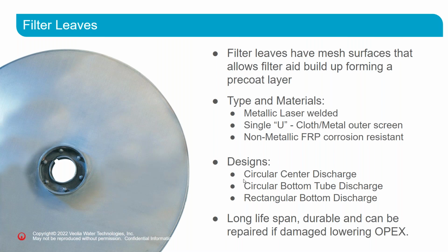We have different designs for the leaves as well. We have the circular center discharge, which is what is shown here. We have the circular bottom tube discharge. Often this is used for dry cake applications. Or we have the rectangular bottom discharge, and this is typically used in our Filtra-Matic filters.